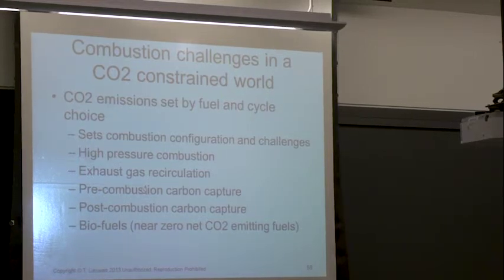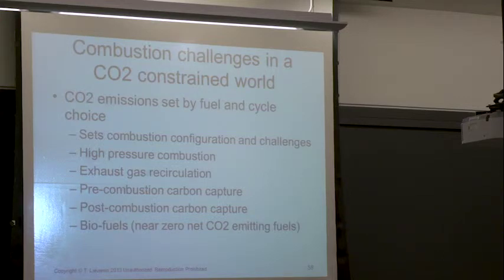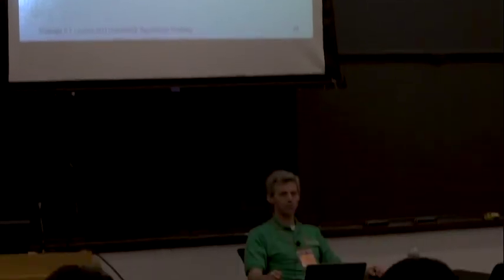Hydrogen is, it's like its own animal. It's like if all of combustion's a cat, high hydrogen's a dog, right? It's just the molecular weight difference between it and everything else is just so profound that hydrogen just acts as a completely different animal. Just think about flame speeds. You know, the flame speed of methane is different from ethane. It's a little bit different from decane, dodecane, etc. But those are, you know, what, 20, 30% differences. Whereas hydrogen, it's an order of magnitude, right? The flame speed of hydrogen is an order of magnitude. Or the molecular weight difference, which affects stretch sensitivity, which we'll talk about later.